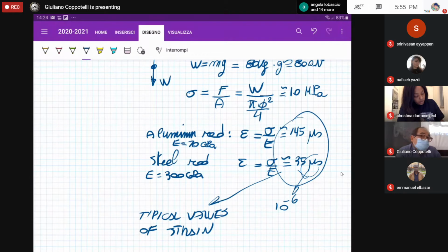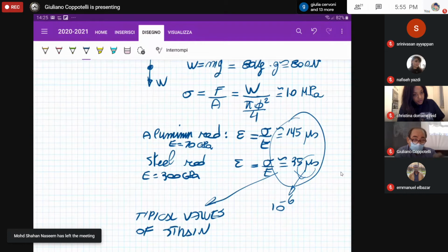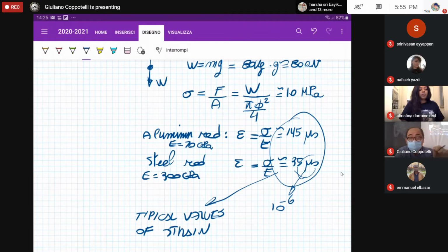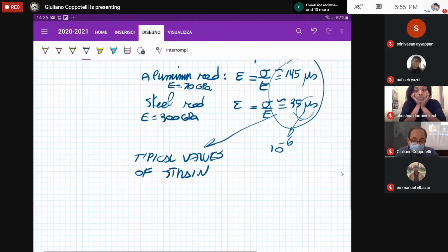That's not just for fun, just having measurements. So the reference, the typical quantities that have to be measured is about 100 microstrain. If you're having thousands of microstrains, then we are going to have a very large strain, okay? So we are almost at the limit of linear elasticity model, okay? Generally, we have about 10 up to 100,000. It's okay, but we are at the border. We are okay with the linear elastic models, generally speaking.